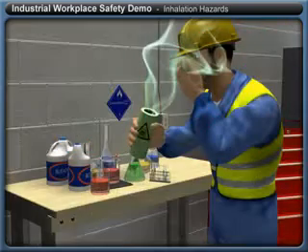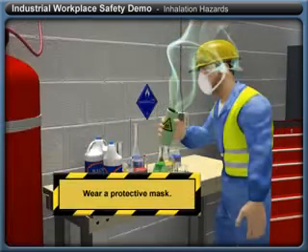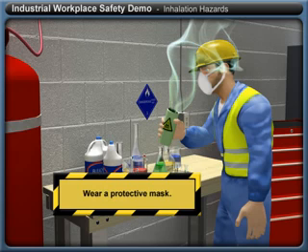An inhalation hazard is the risk of breathing in any substance that is harmful. Some materials that emit harmful fumes include fuel, hydraulic fluid, and antifreeze. You can suffer headaches, weakness, nausea, pneumonia, and lung damage. Wear a protective mask when working with any of these fluids, or when sanding paint or grinding metal, since the particles emitted can irritate your respiratory tract.